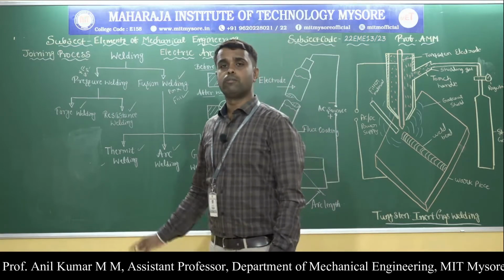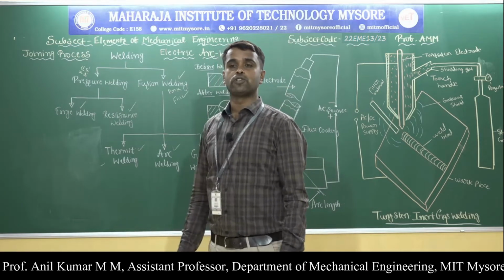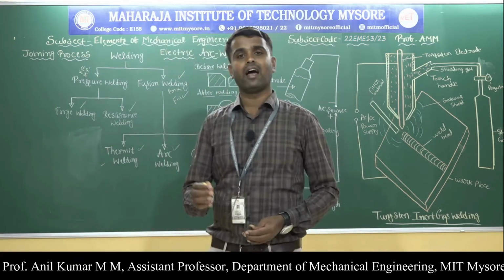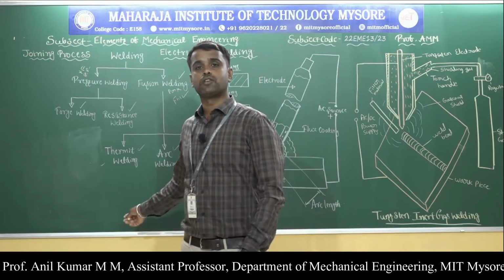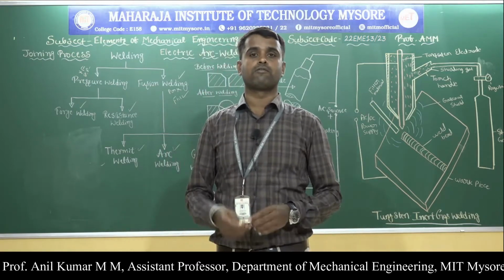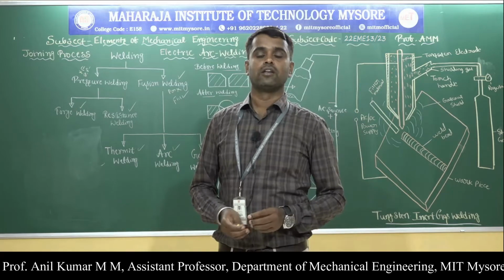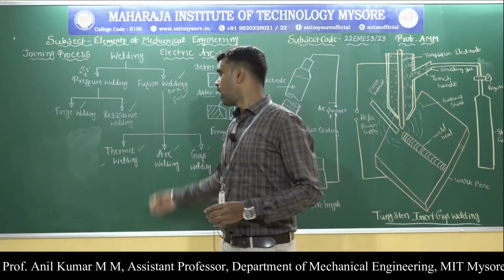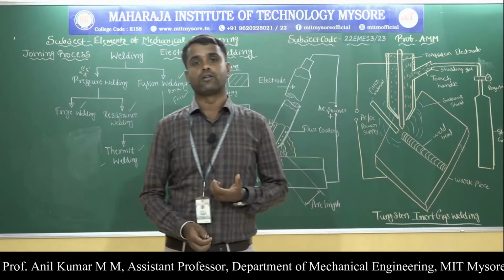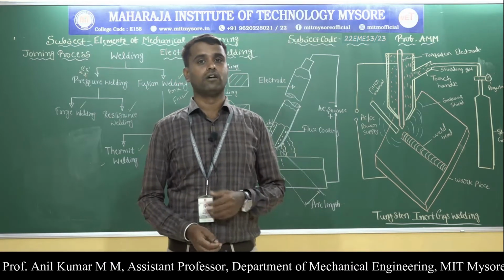Internal stresses are developed during the welding process, and high temperature is involved. So there are changes in the microstructure of the base metal. If the microstructure changes, the properties of the material will change. Care should be taken, and skilled workers are required for producing a good, solid joint. These are the disadvantages of welding.